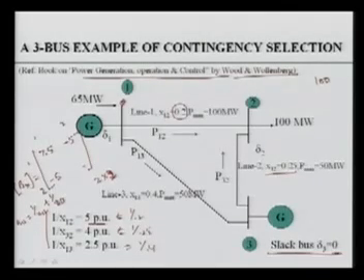Now here the value we are going to calculate is a diagonal element, and that diagonal element is nothing but the summation of admittances of those lines that are connected at bus 2. So here 1 upon 0.2 plus 1 upon 0.25. So this will be equal to 4 and 5, it will be your 9. So this is your Bx matrix. So it is very easy to form.